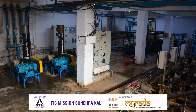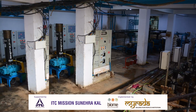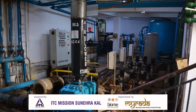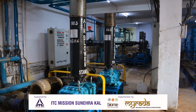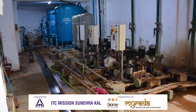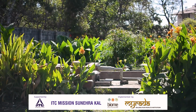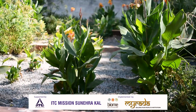Wastewater that is generated in an apartment can be very easily treated in an STP. STPs follow different kinds of technologies. The commonly used one is the activated sludge process, then there is a sequential batch reactor. There is a range of technologies. These are electromechanical STPs. You could also have low energy plant-based STPs which use similar technologies but which are slightly slower in process and give you treated wastewater as well.